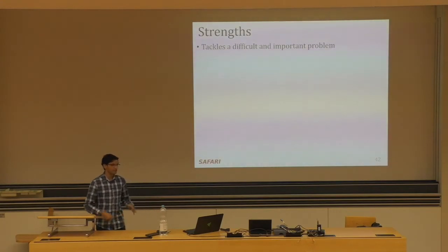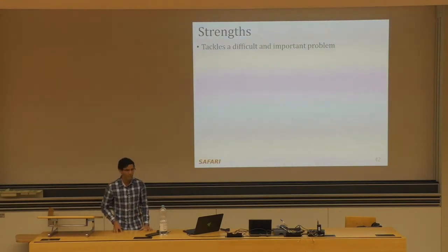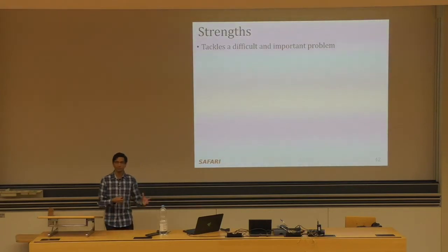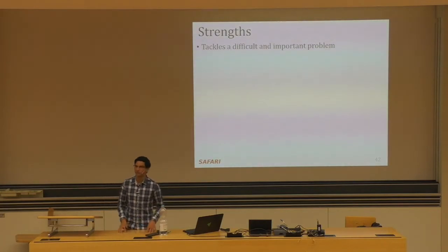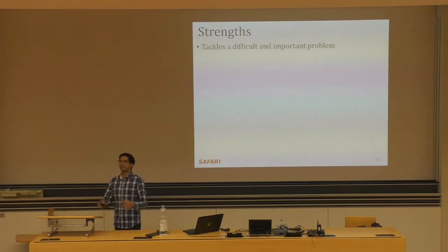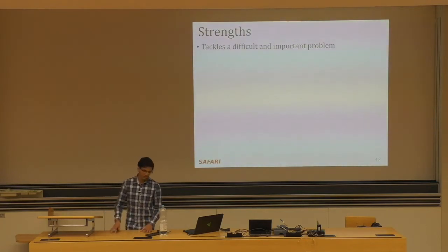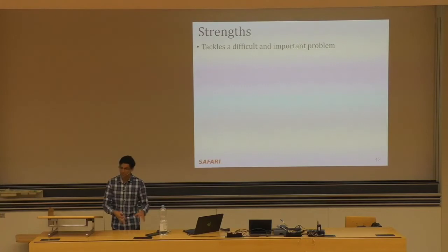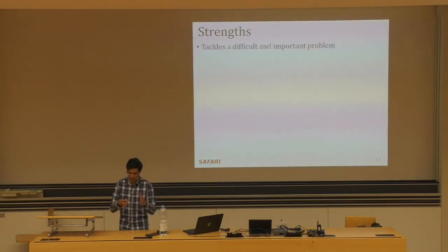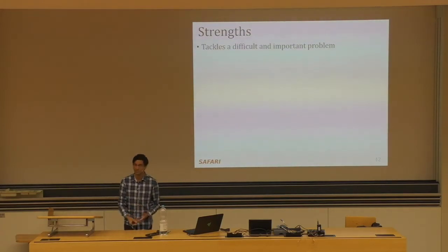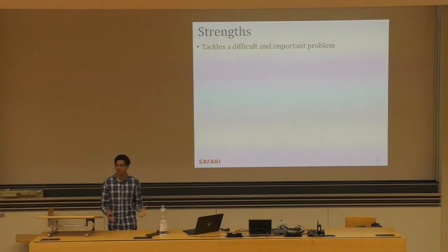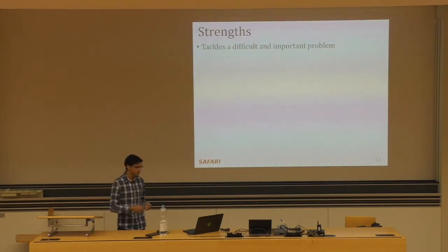So the first strength that I have is that this paper tackles a difficult and important problem. And I hope through talking about the challenges of profiling that I've convinced you that there's a lot of effects here that are very probabilistic and hard to manage. And that makes this a difficult problem to fully solve, right? Because we can talk about having, say, 99% coverage of errors or 99.9, but it's very difficult to say 100% coverage because these retention times are changing all the time, right? And so what's true for a single instant in time is not true always, right? And this is why we need online profiling and to continuously do this. And inherently, it's a very high overhead process, right? And so by amortizing it over all of runtime, it can provide a good trade-off point, which was what I was trying to show in the performance results.